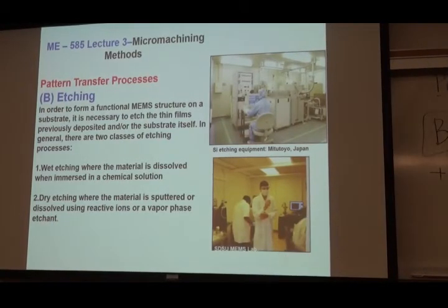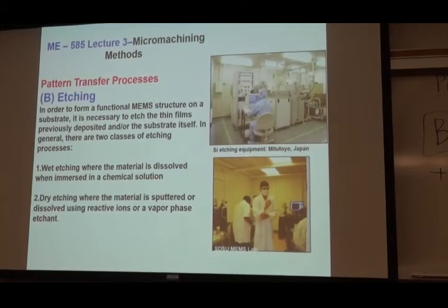There are some professors who come to the clean room and they run away, and I think, oh, these ignorant guys. But anyway, BHF is buffered, it's less corrosive, it's in a liquid environment. It's not gas. But it does the majority of stuff that I wanted to do, the same way as HF. So that's what I want you to remember in terms of etching. Any questions?